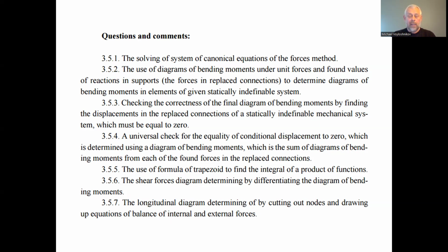How to do that? The displacement of the points in the supports has to be equal to 0, especially in the supports we cut off when determining the statically definable main system of the assigned statically indefinable system.